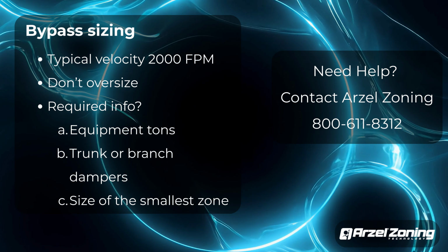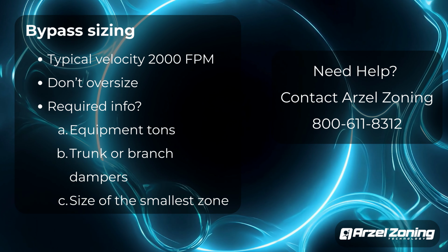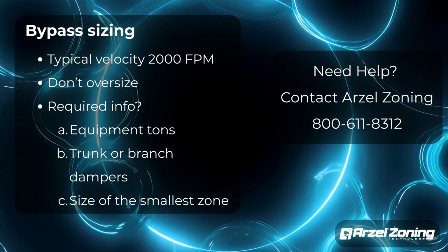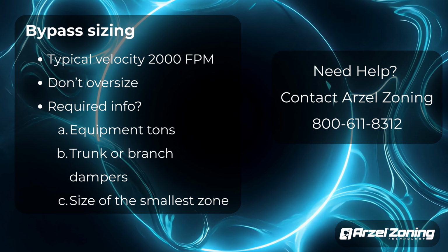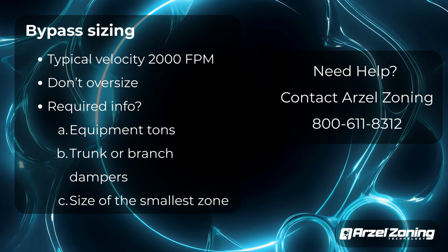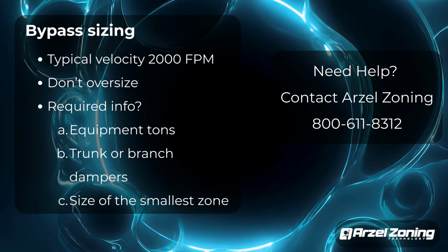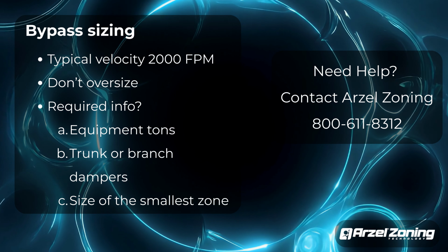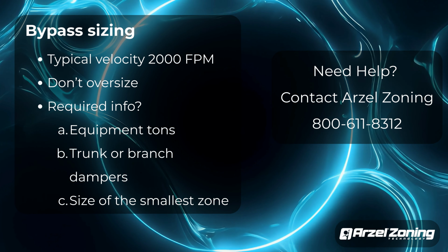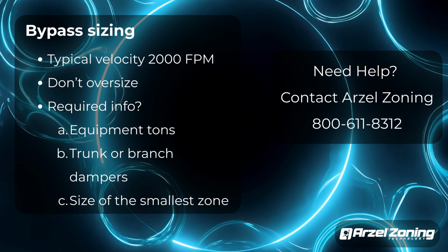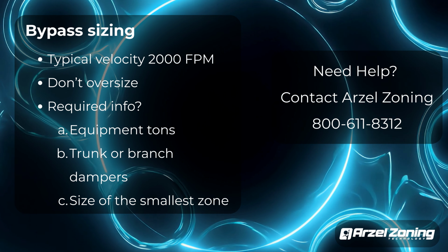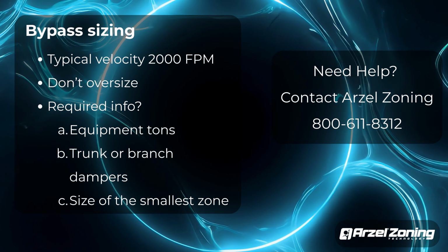Our average bypass that we sell is the 8-inch. It can move somewhere around 750 to 800 CFM of air, max. Most are not moving that, but we were floored to find out through testing with professionals that this kind of velocity was being reached. Now, that's the average. We saw sometimes 1,500, we saw as high as almost 2,500 foot per minute velocity. But that would take a very small damper and steal a lot of valuable airflow and static pressure if you didn't adjust it correctly.